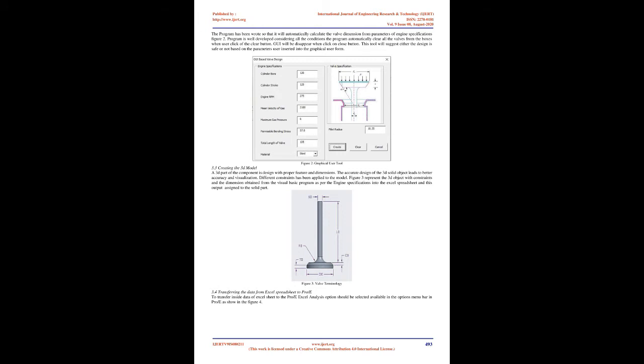Here in Pro/Engineering, the Microsoft Excel spreadsheet is integrated with the Excel analysis feature. Excel analysis is the feature useful to interact with the Excel cells' text data in Creo. The Excel analysis tool transfers the Excel spreadsheet data to the Pro/E database.